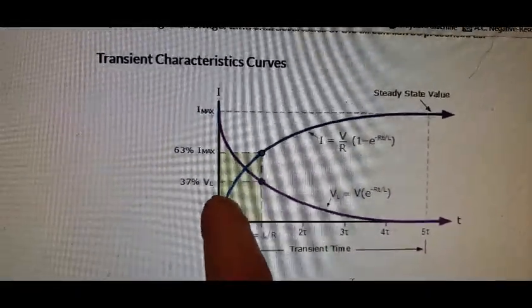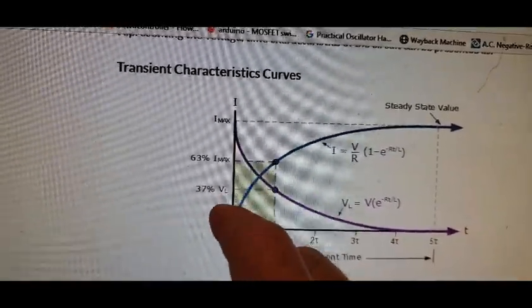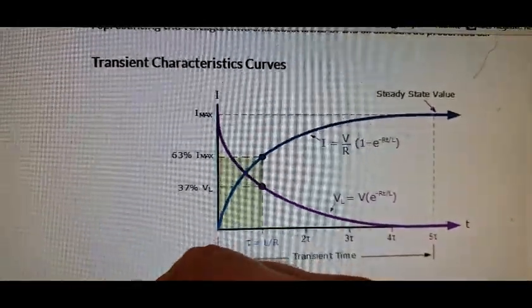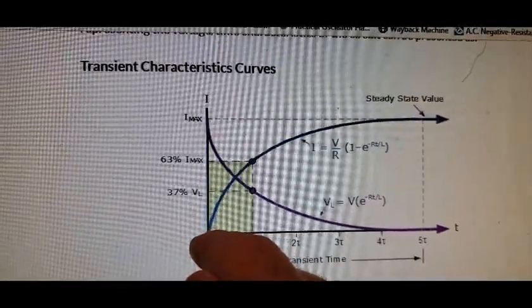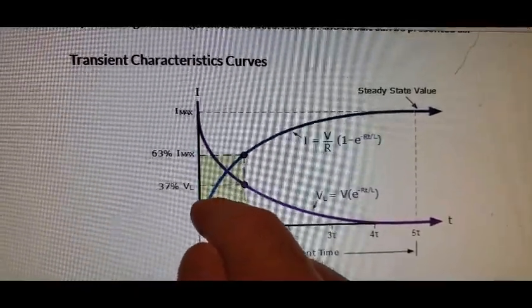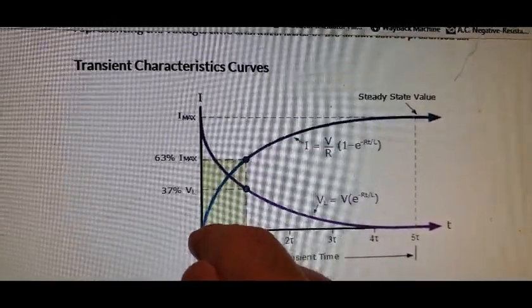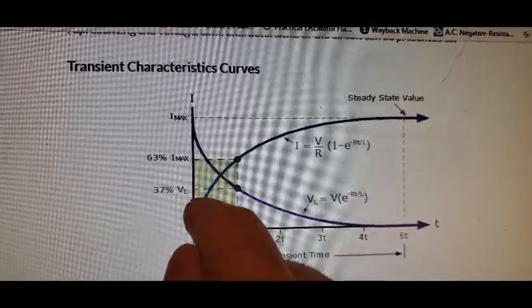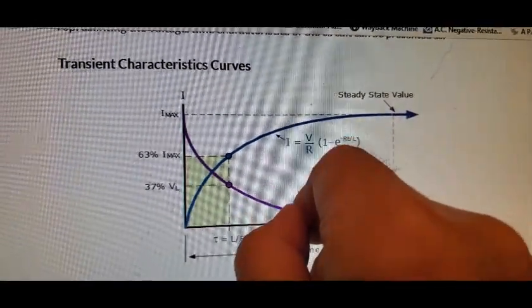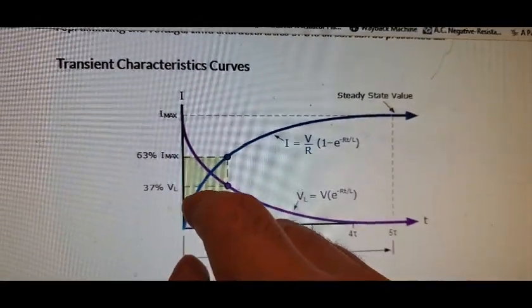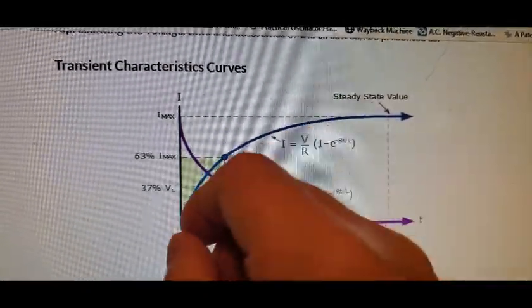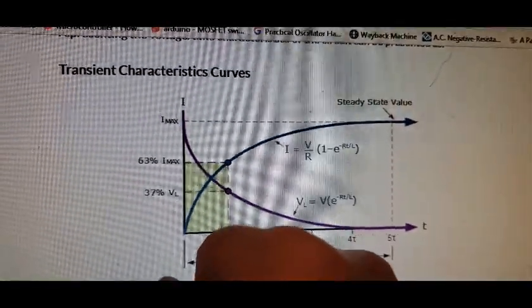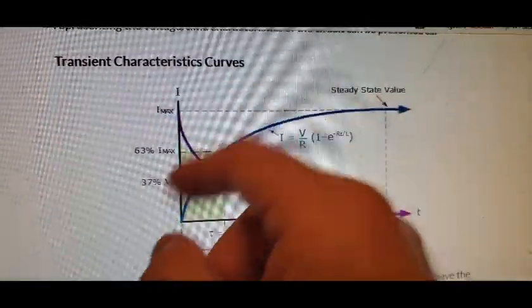Now, of course, that doesn't mean that your inductive spike gets bigger the faster you're going. The inductive spike is getting smaller and the voltage is getting lower, but the relationship between the amount of coulombs of charge you expended in order to get a particular strength of magnetic field, as compared to the collapse for the spike, is always improving as you're going down here until you run into other issues. And those can be issues with your components.